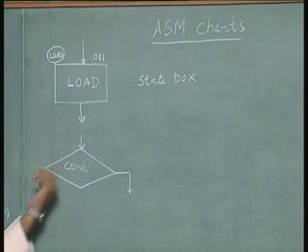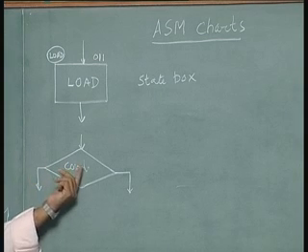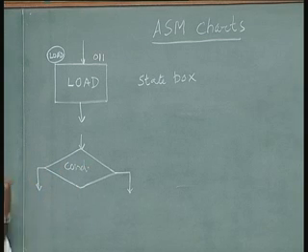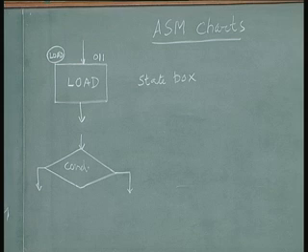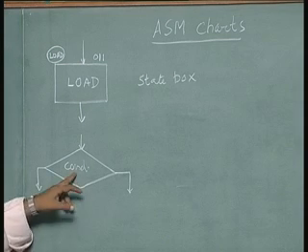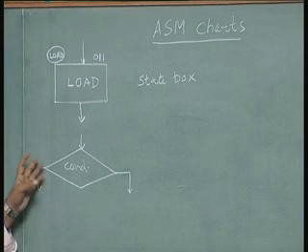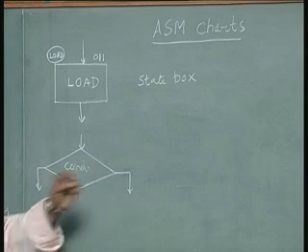If it is available, you will want to start and proceed. If it is not available, you will want to wait. This could be an example of a conditional verification, or it could be a memory read operation with wait state, where we are looking for some data ready signal coming from the memory. So you can say data ready: if no, wait; if yes, proceed.